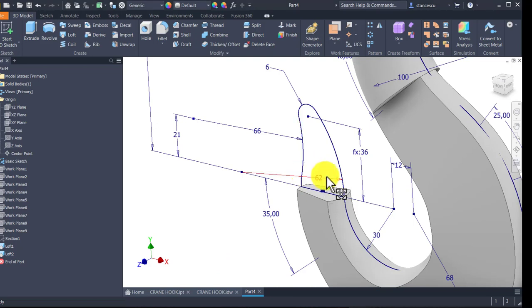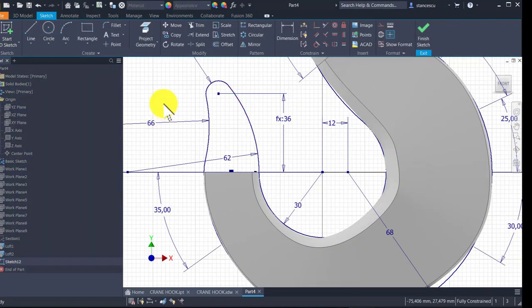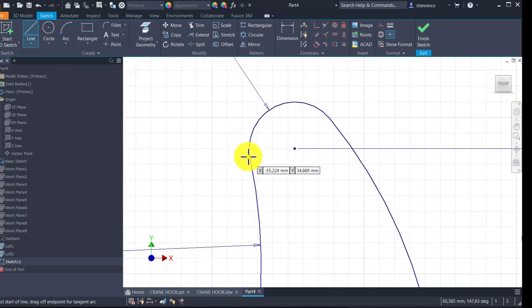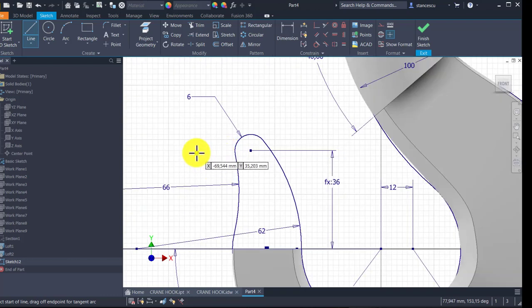We have to create new sections here, and I project in a new sketch in the plane XY. I select the plane and I select sketch, new sketch. Here I draw a line between connections of the two, but I have to project.